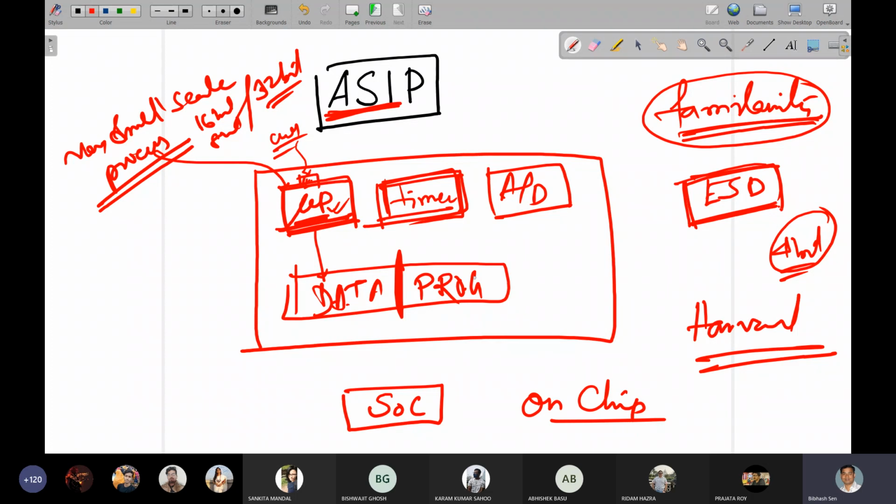In von Neumann architecture it is also a stored program concept, but when you go for the von Neumann Princeton architecture, data and program are stored in a single memory, whereas in Harvard architecture they can be separated. For the purpose of your design, sometimes separate data memory and separate program memory may be required. So speed will be enhanced; though the area will be more, the speed of the device will increase because separate bus lines are used to access data and program.